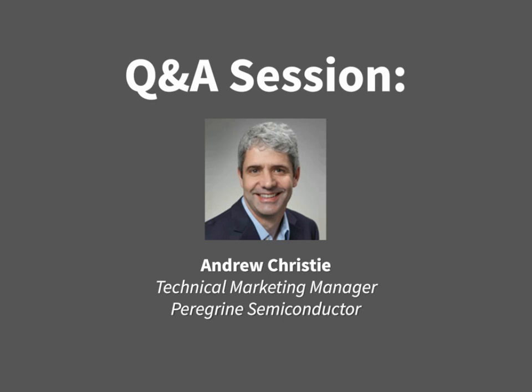The next one is, does the antenna and the path to the antenna need to be accounted for in proper beamforming? So I think that depends. I think yes, it does in principle. The reason it would be important would be if there were different length paths with different delays between the output of the beamforming array and the antenna array. So if each antenna element had a different length path, that would need to be corrected for somewhere in the system.